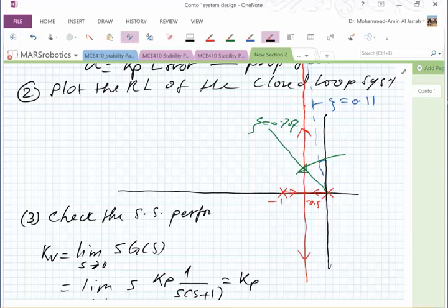What kind of controller should we add that will improve the steady-state response? Proportional integral. Well, this is general because PID is used for all. The question again: how do we improve the steady-state performance of the system? You remember that to improve the steady-state error, if I increase the type of the system by 1, I reduce the error. So the ramp error becomes 0 all of a sudden, for any combination. So I don't need to worry about the error in this case. So what is the solution for this? To add an integrator.